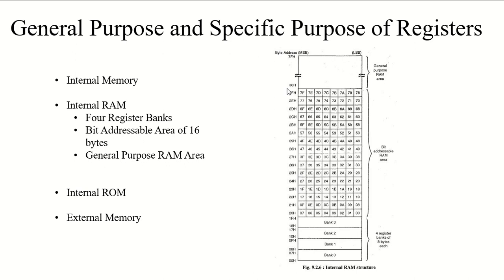And this RAM area is also called the scratch pad area. Sometimes it lies above the bit addressable area and has addresses 30H to 7FH, as I've said. And this RAM area can be used as data RAM as well. So the memory in this area is byte addressable memory, right?